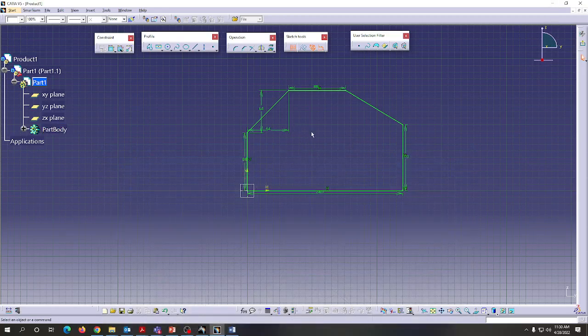Whenever you do sketches, it is very important which mode and which point you have to start from, and whether you need to cover the positive axis or all the 4 axes. According to the sketch, and it will come only by practice. So now we have given all these constraints, all the dimensions. Our sketch is aligned. Before I had given this vertical line and this horizontal line, my slanting line disappeared. It means the sketch is aligned with the given dimensions. Whatever my requirement was, it has not appeared.